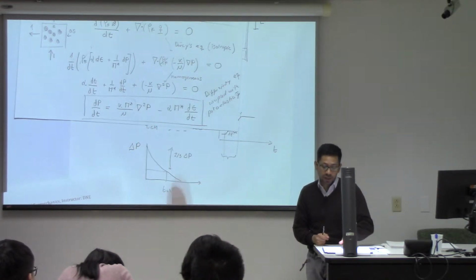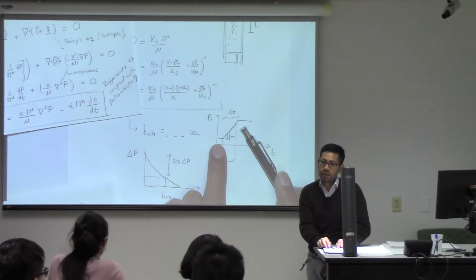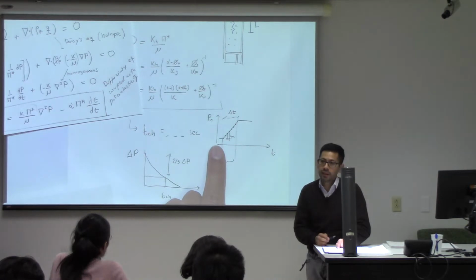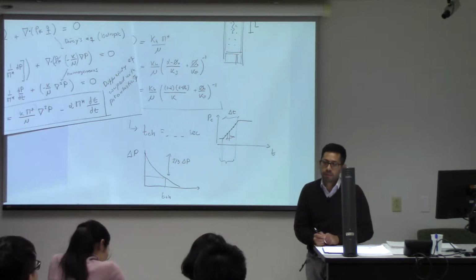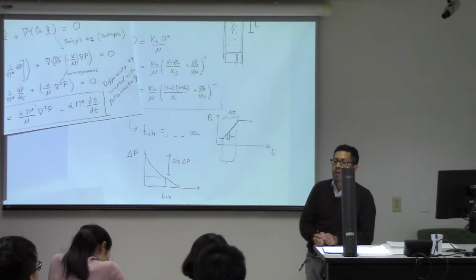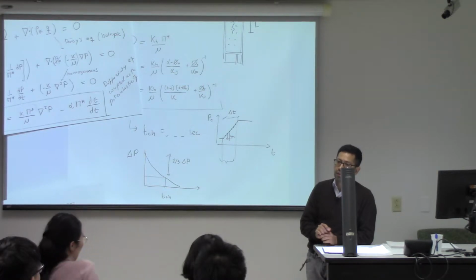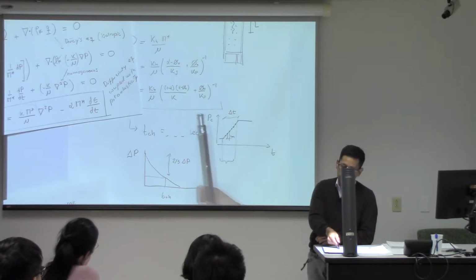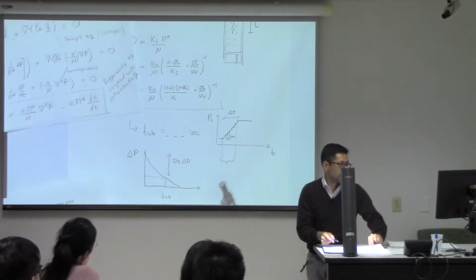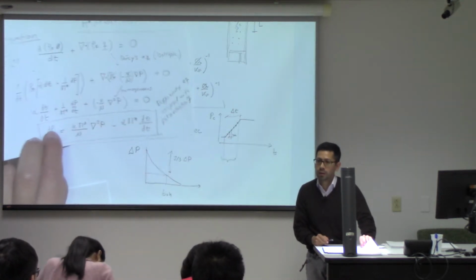But just in general terms, I will go by comparing the entire cycle length to the characteristic time. That characteristic time is always going to be the same. It's essentially an assumption in a way. I would say it's just a short way of comparing the time for drainage with the time of loading. But we could add here a speed of loading, and if you were to solve that equation, you should be able to see if you have undrained loading or not. Okay?